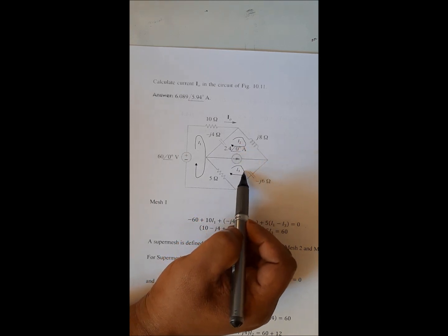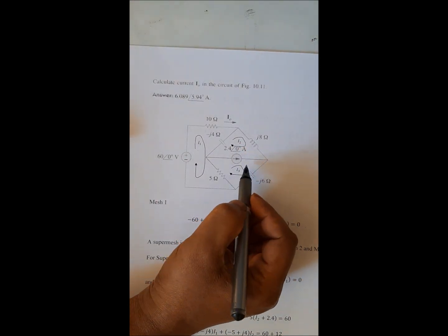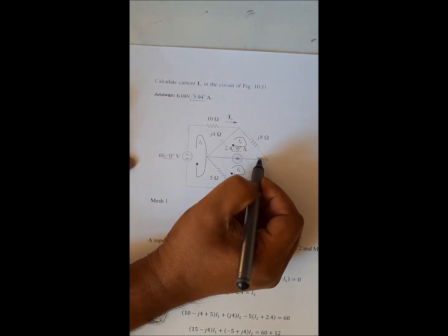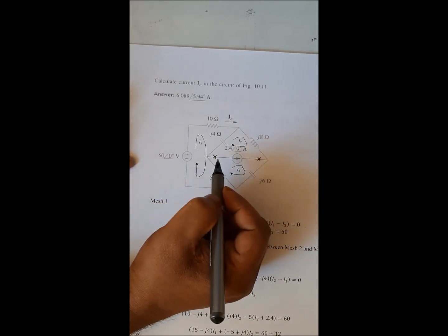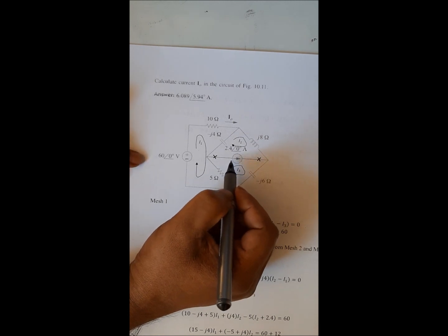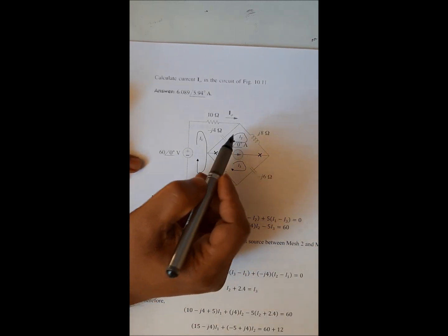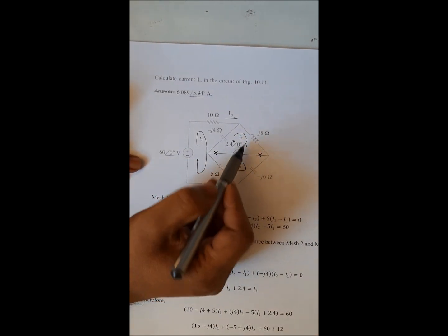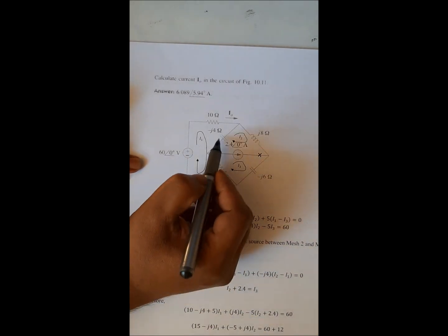Also this current source is shared with I3, so we cannot pass through this branch, so we can skip this branch and form a super mesh. So now we write a super mesh here including mesh 2 and mesh 3. So mesh 2 has 8ji2 and mesh 3 has negative 46i3, then 5i3 minus i1 and negative 4j i2 minus